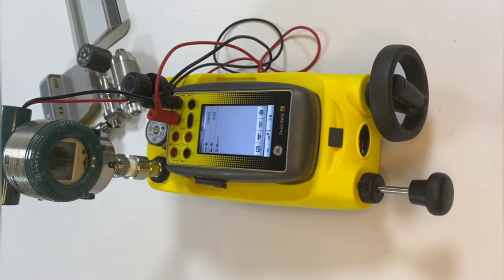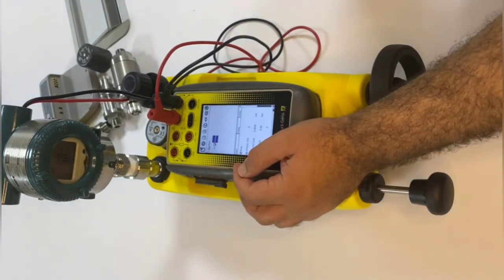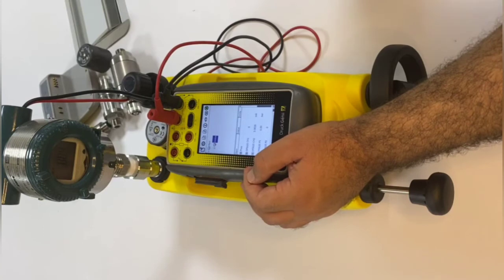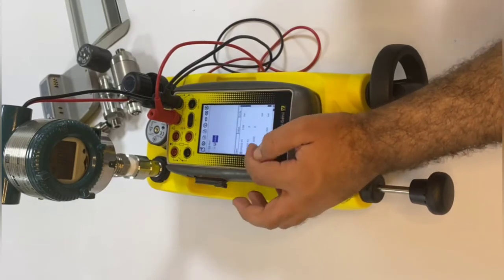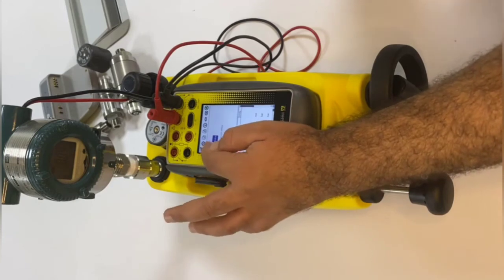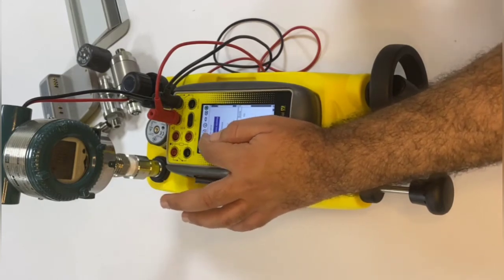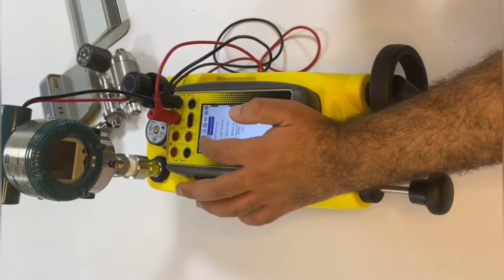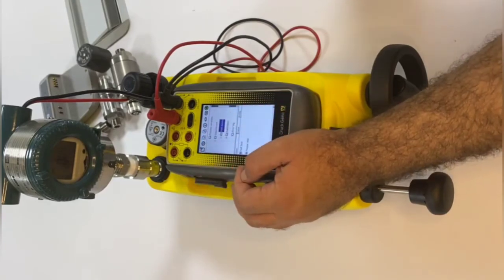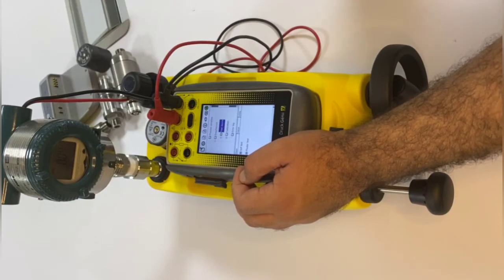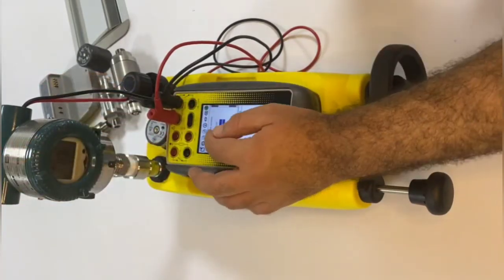Then I can log in and perform the adjustment if required. So let's just quickly navigate through the HART to brief you about the functions you have in that. So anything in red we cannot change, anything in blue is coming from the calibrator side, anything in black is editable. Here are the information. So under the device setup, I have process variables, diagnostics, services. I can do a test device, self-test or master test. These all are enabled or disabled by the manufacturer of the transmitter.